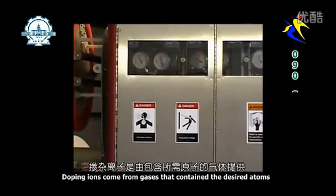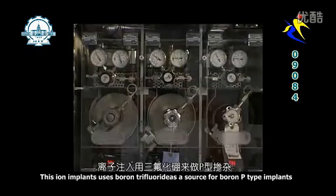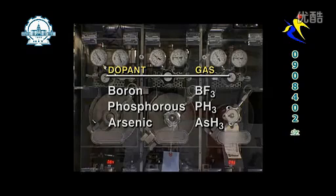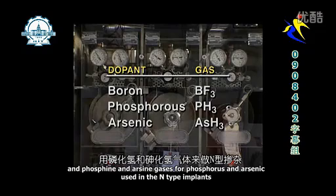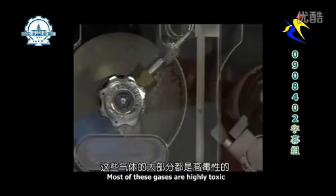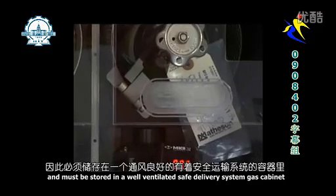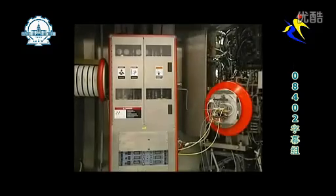Dopant ions come from gases that contain the desired atoms. This ion implanter uses boron trifluoride as the source for the boron p-type implants, and phosphine and arsine gases for phosphorus and arsenic ions used in the n-type implants. Most of these gases are highly toxic and must be stored in a well-ventilated, safe delivery system gas cabinet.